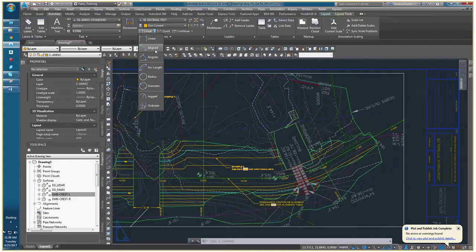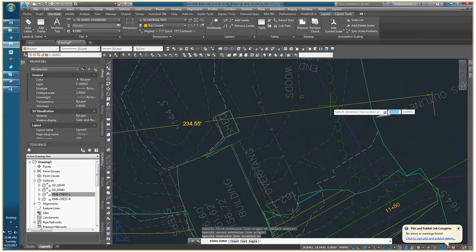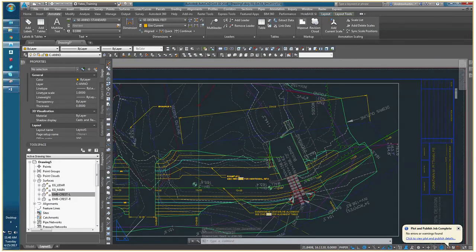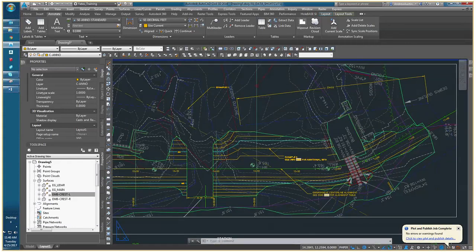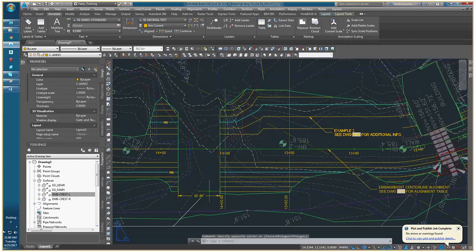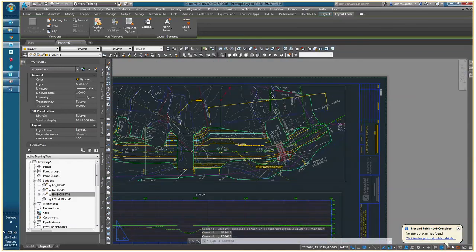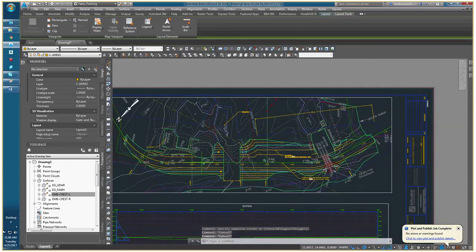paperspace usually works perfectly without any sort of hitch. It knows what scale the drawing's at, and it can define that length very, very easily. With surfaces, there's just more going on there in terms of elevations and stuff like that. It wasn't able to determine the model space length as quickly and easily, and so it gave me a paperspace length of 1 inch plus. And that's why I was forced to put this one into model space, but I was not forced to put this dimension in the model space. It's living in paperspace.